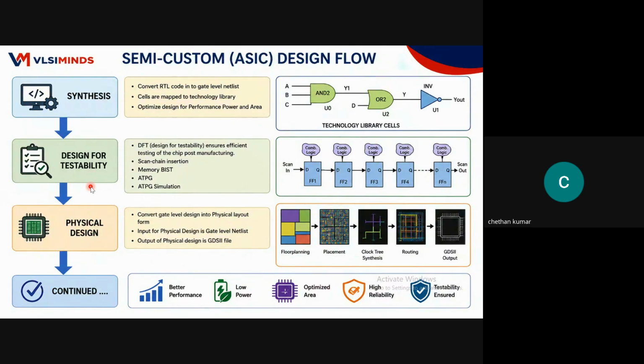See, all these keep going, right? The RTL designer will give the code, it will be verified by the design verification team, it will go to synthesis, and then physical design will take care. Why do we need a DFT team here? The DFT team is mainly not involved in anything related to the functionality. The DFT engineer will mainly be involved in adding extra logic which can detect manufacturing defects.